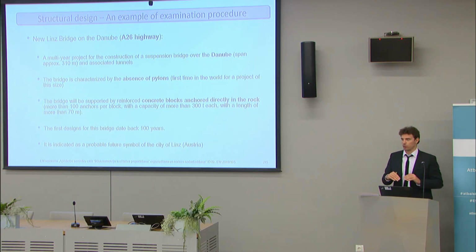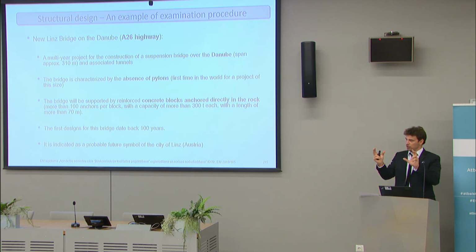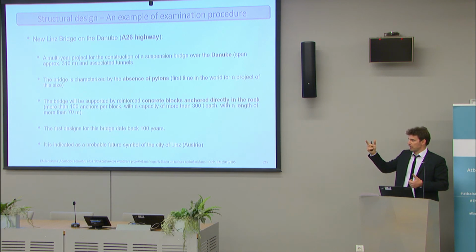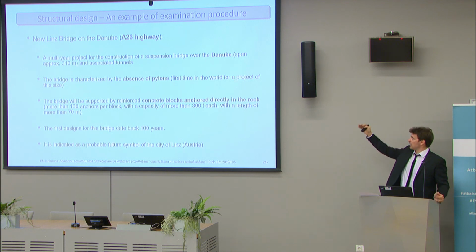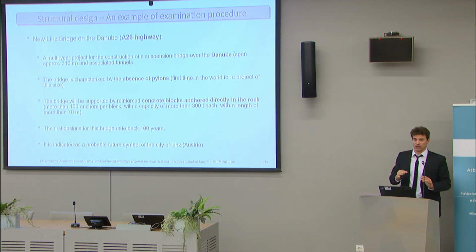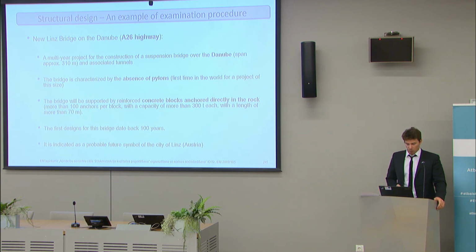So when they mount the structure, they need provisory boats that bring the pieces of the bridge, and they are going to give a counteraction upward because they have to deform the bridge in this way. Then when it is charged by that load, it assumes the right deformation. So it is something that they have to do on a provisory boat, and they have jacks that must push more than 8 tons, and they are about 2.5 meters high. So it's a very, very complicated montage as well. The mounting of the structure is going to be quite complicated as well.